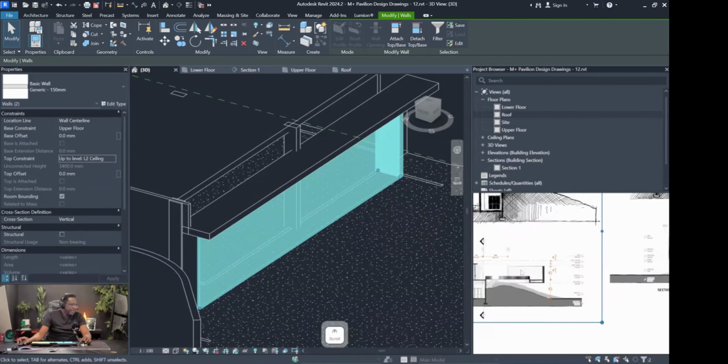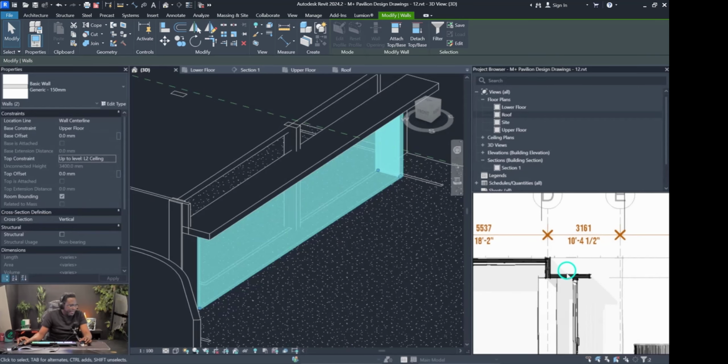All right. Another thing, because this is a sketch, we don't really have the thickness of this, but I would gather 300 millimeters, or a foot, would be quite thick. So I am going to go ahead and change the basic roof, generic roof 300 millimeter. And for now, I'm going to go to edit, and I'm going to change the structure of that to 150 millimeters. I'm going to choose OK. So then that will adjust the thickness of these roofs.